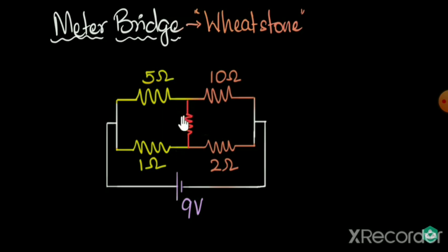and you have a resistor in between. And the whole idea is, if the resistances have the same ratio, like in this example, 1:2, 1:2, then the voltage here and here will be exactly the same, and as a result we'll find no current flowing through this resistor. So the current over here would become 0, provided these have the same ratio. And it doesn't matter what this resistance value is, or what the value of the battery voltage is, or even the value of the resistors. All that matters is that the ratio over here should be exactly equal.